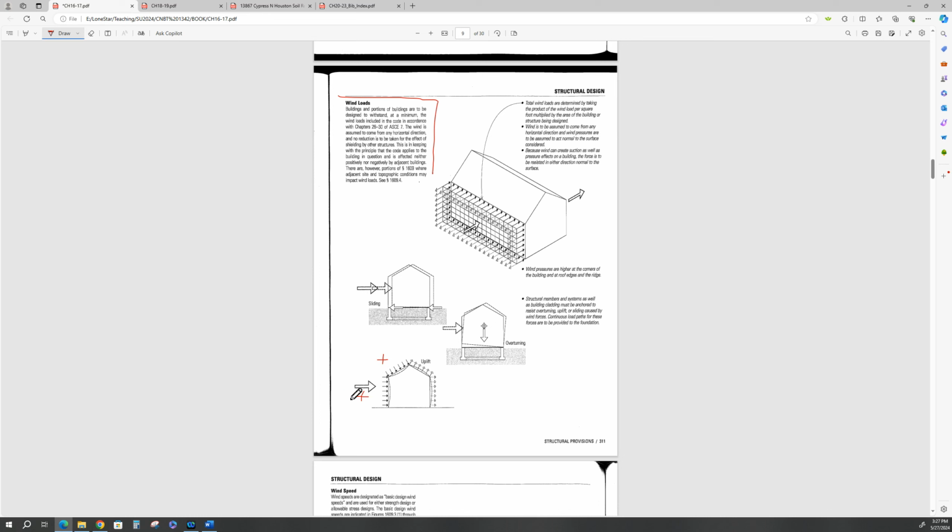But when the wind comes up over the top, it pushes on this, but makes the crest, and then this is the leeward side. The wind's still going. It's going around the building too. This is negative pressure. This is negative pressure. There's suction over here and pushing over here. You're pushing and you're pulling.